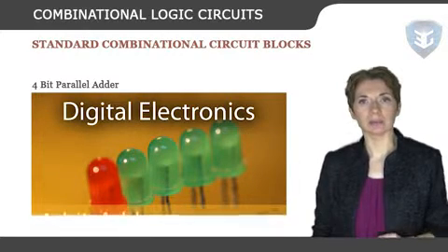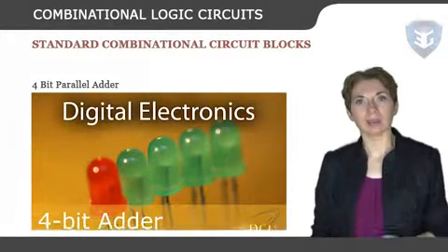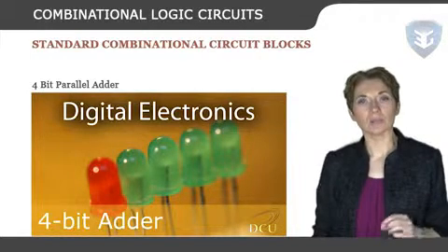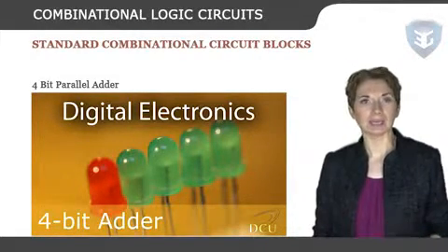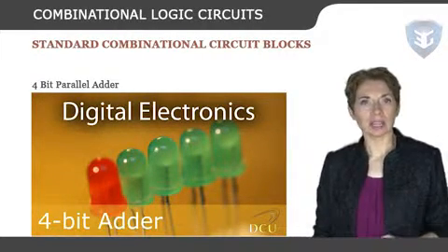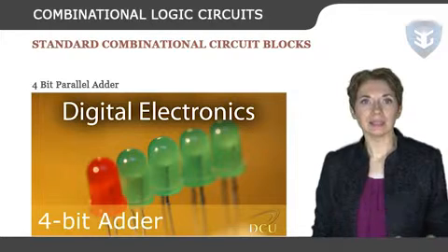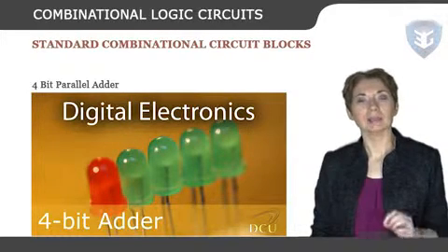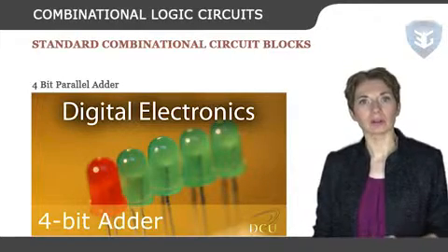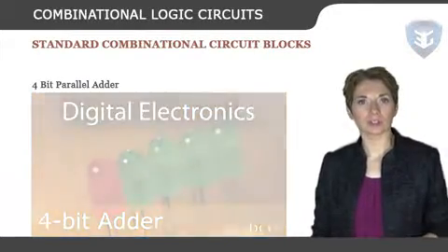4-bit parallel adder. In the block diagram, A0 and B0 represent the LSB of the 4-bit words A and B. Hence, full adder 0 is the lowest stage. Hence, its CIN has been permanently made 0. The 4-bit parallel adder is a very common logic circuit.